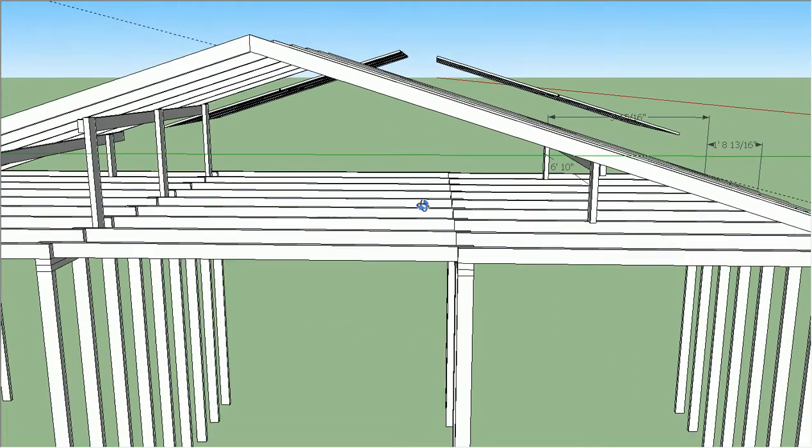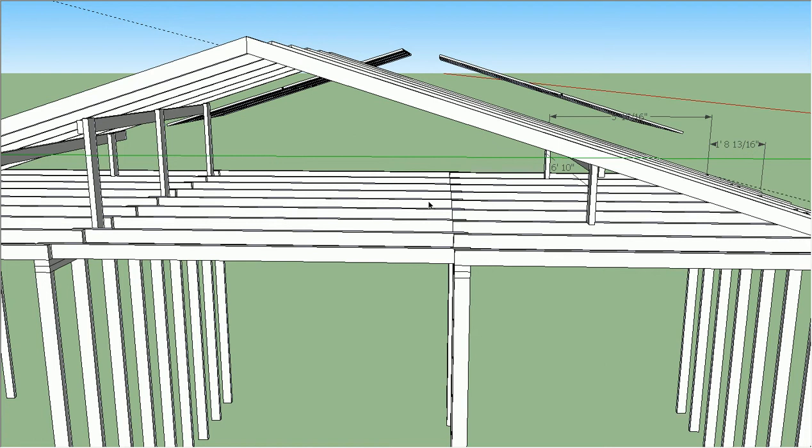But as far as the information that needs to be recorded during the audit, I try to make a relatively easy mnemonic to remember things, and it's basically you want to always record the 3 S's, which are the size, the spacing, and the span for every structural element until the load makes it to the wall. So that can be a lot to digest in one sentence. So that's kind of why I've made this video, to illustrate what I mean by that.